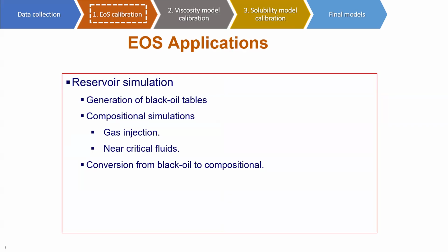The oil has an initial gas in solution, the solution gas, but if you inject more gas into this oil, it can enhance your initial volume, and this enhanced volume can reduce the viscosity. This is called oil swelling. You can simulate this using the equation of state, and the black oil tables need to be extrapolated beyond the initial bubble pressure.